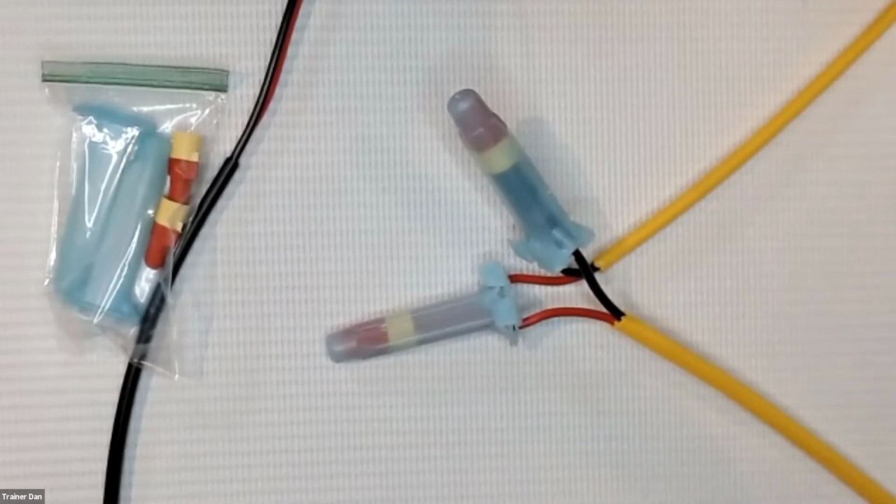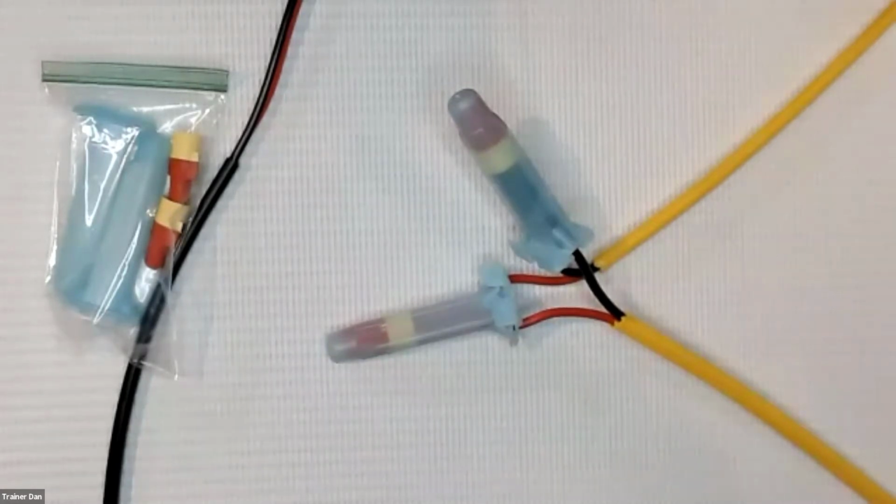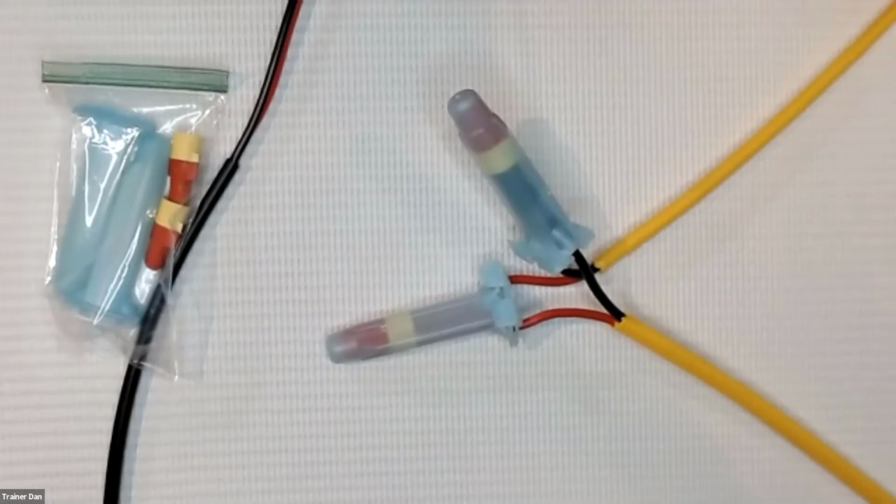Right on, for performance. If you're not using double jacketed, double insulated, solid copper core wiring, that does not meet our specification, so be mindful of that. And don't ever use any kind of stranded wire for two-wire. Are you saying that from experience, Chris? Yes, I am.